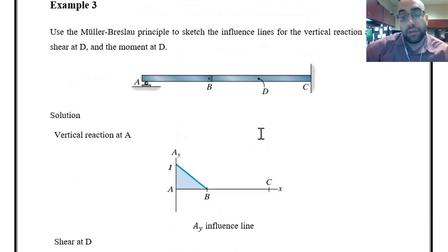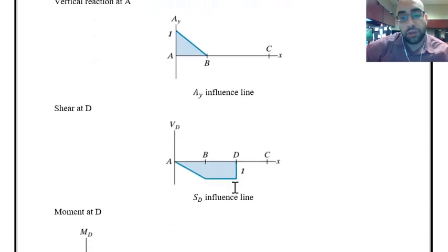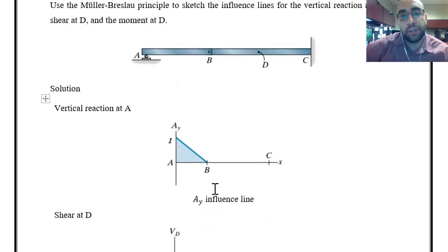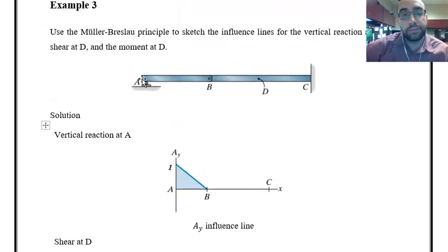That's because we are keeping the moment restriction as it is. We have not removed that, so the two lines, or the left side and right side, should be parallel. That's why we have such a configuration. And then at B I have a hinge, so it can have rotation and it should return to its original location at point A because we have the support over there. It cannot experience any displacement.